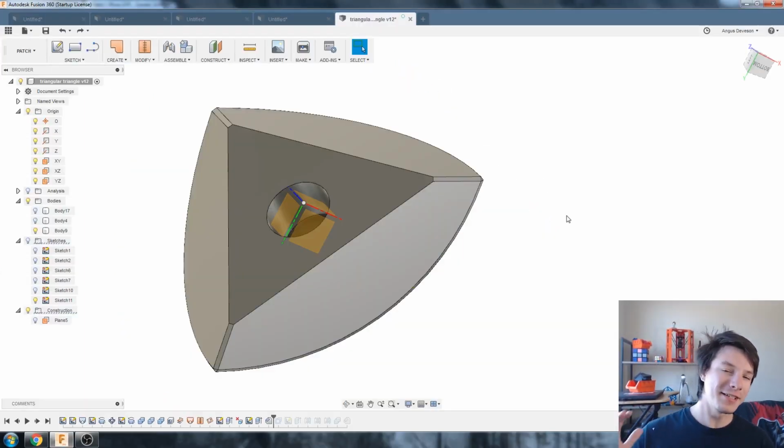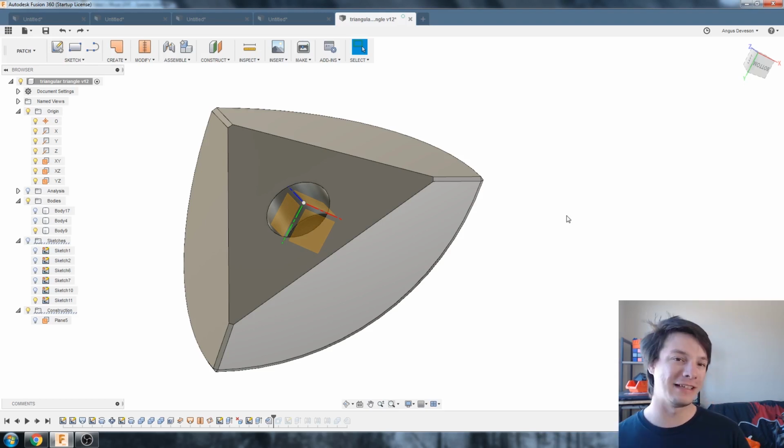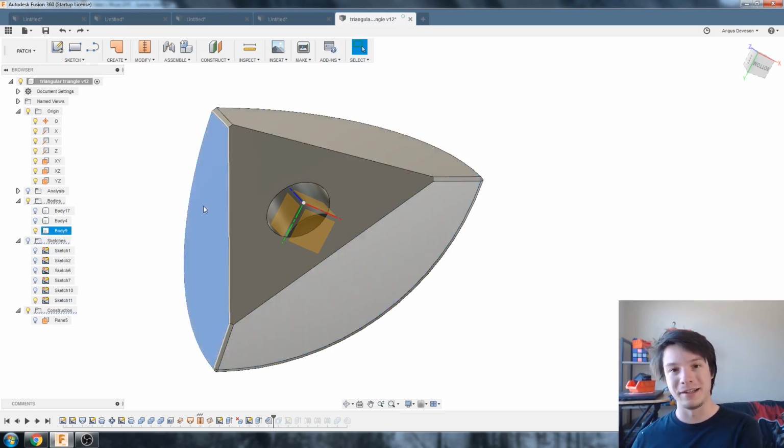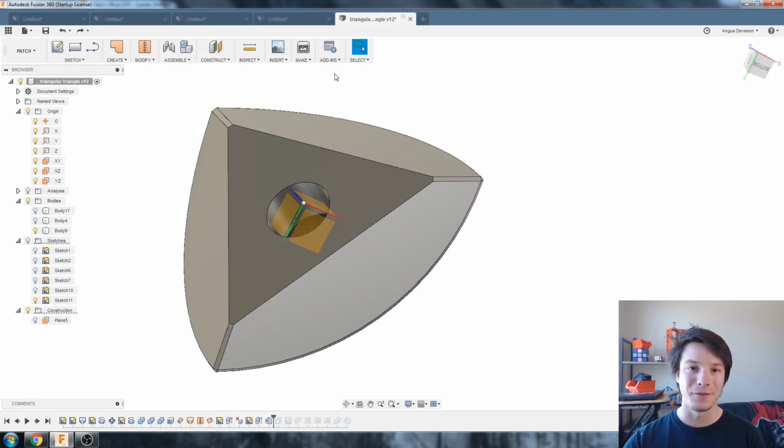Okay, now this is where I ran into a little bit of an issue. So you generally want to try to think way ahead in terms of 3D modeling like this in Fusion 360, parametrically. And I want clearance between my parts because 3D printing isn't going to be perfect. And we've got a 0 thickness between the parts currently, whereas if we print them, we need some clearance. However, to create my center peg, I need to do a mirror, and I'm going to need to use these faces here to do it, which I'm going to move by doing an offset for clearance. So I'm going to just preserve them by using another patch. This is using patches as construction geometry. It's totally cool. It's fine. It's a really good way of making sure things don't move when you might modify the shape.